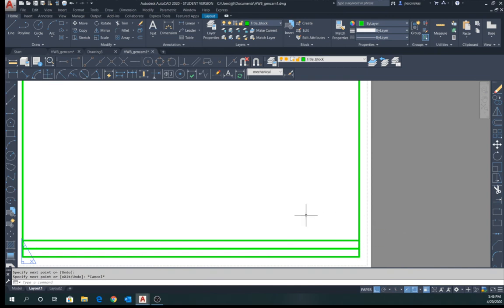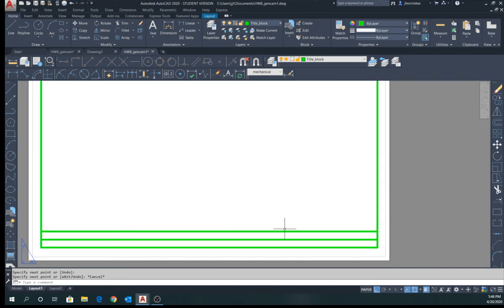So I did snap at that point. I'm going to stop my line, and I'm going to come look down here, and let's see: ISO draft, restrict to specified angles off, snap to 2D reference points, show snapping reference lines. Polar tracking. Do we actually need to have the polar tracking instead of the ortho tracking?